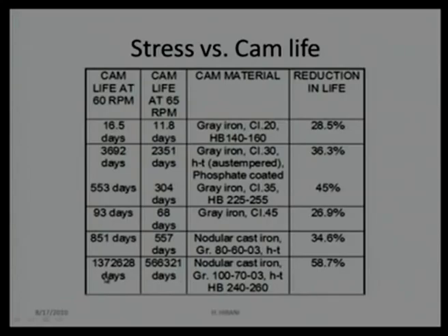So, in total, when we do a wear analysis for this kind of mechanism, we can compare the materials, we can find out what kind of load condition is going to give us a good solution. Do we need to reduce the load magnitude? Do we change variation in the load? If yes, whether that is going to be advantageous to us or not. If we find no, even whatever I do cannot change the dynamic load because of the rolling contact, which has inherent dynamic load generation, then there is no point to change the design at that point.